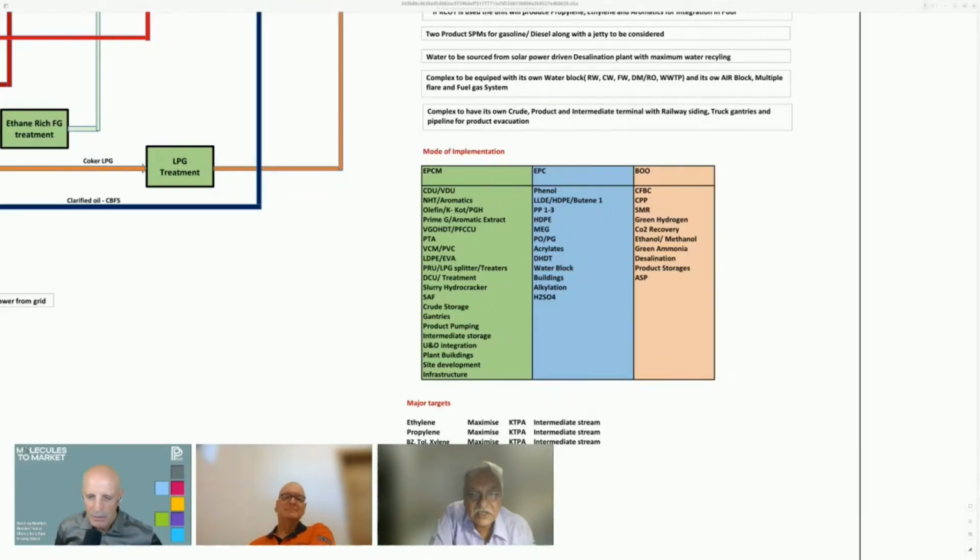Yeah. So actually, in India, our experience has been that this number varies from 22 to 40%. So the risk margin built in can be as high as that, because there is a price reduction clause. Then there are so many risks which the contractor has to take. So this can be a margin, and quite a bit is a delta, which is a penalty to the owner in terms of cost. So our understanding is that if you go for an EPC route, it is neither schedule friendly nor cost effective.